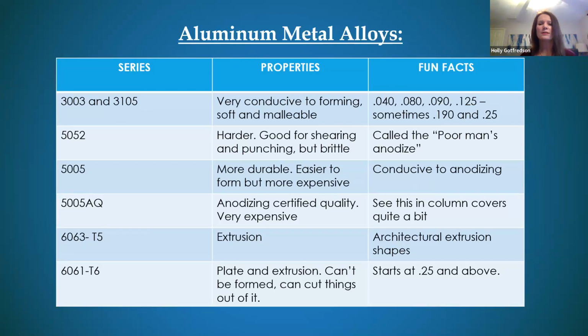And also you want to consider, what are the processes that occur with anodizing versus, let's say, liquid painting. Anodizing is a chemical process. It's pretty harsh. It's very tough on the environment. You also may run the risk of what's called checkerboarding. So typically your perforated product or panel is going to be in a dip tank. It's going to be dipped for that anodized finish. If you look at panel 1 versus panel 500, there's definitely going to be a difference in color and finish.